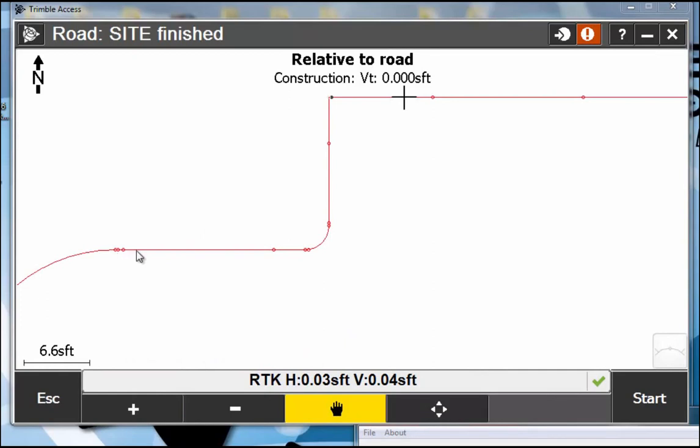So it's automatically going to put in PCs, PTs, VPIs, or PBs. I don't see a midpoint on that. I think I have to specify that in what I'm doing. So there are ways in here you can have it put in a radius point and things like that. It's just we don't have it set up that way. But it should. Low points, stuff like that too? Yep, it should. Well, I don't know about high points and low points. We'd have to dig into that.